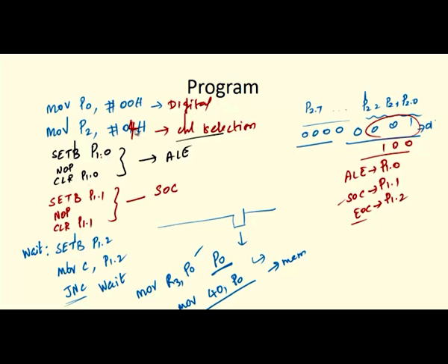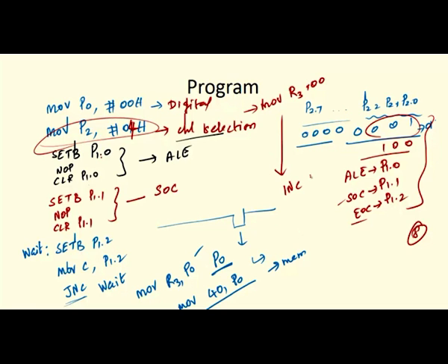Suppose I ask you to read all the channels. All the channels means I have to initialize 8 values, right. So, you initialize a counter; here you can give move R3 comma 00. After each process you can increase R3. Initially it is 0, then by increasing it you get channel 1, then channel 2, channel 3, and so on.